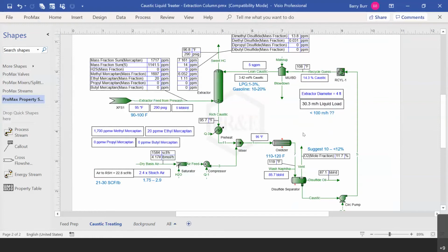So the amount of catalyst is never measured. It's a qualitative test to see if the amount of catalyst is sufficient. And it's just a liquid that you add into your circulating caustic. So it's just a liquid that's circulating along with the caustic. And whenever you find out that you don't pass the shake test, you add some catalyst liquid to the solution and then go out and perform the test a little bit later on. But the model here assumes that there is sufficient catalyst circulating with the caustic, so that everything else about the reaction will be calculated properly.